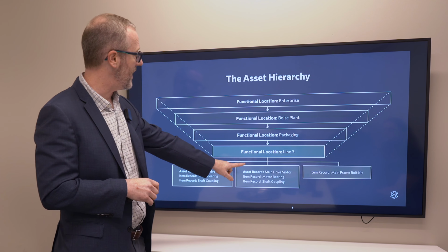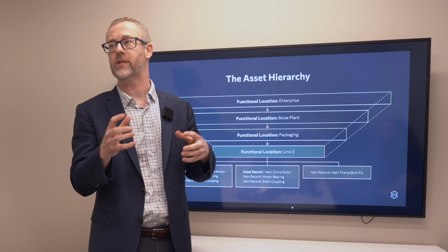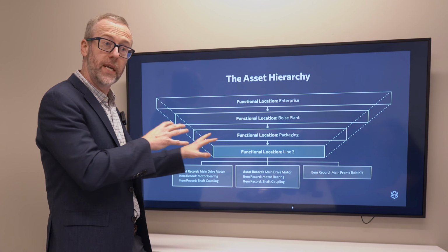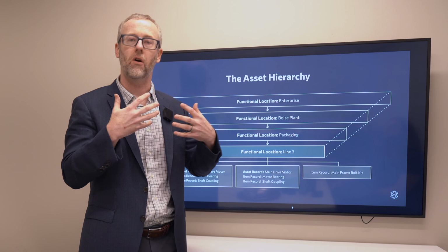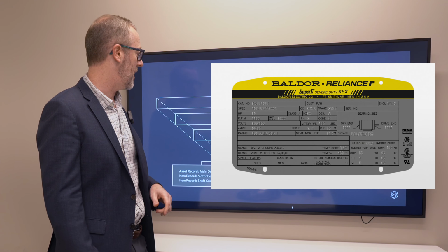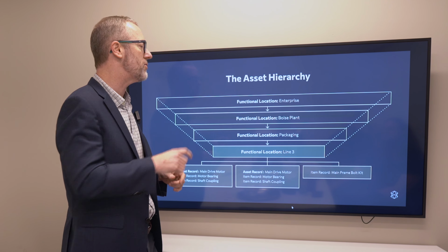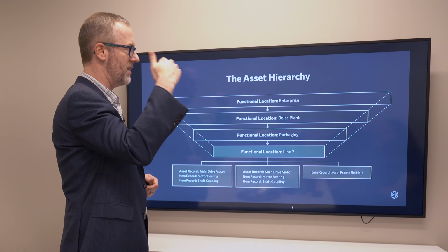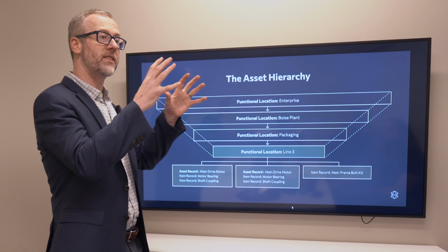The type of information that we need on the asset record is all of the technical specifications or the nameplate details about that asset. Because now, for the asset, this is where we're launching our work orders, so we need to know literally what is the make, what is the model, what type of bearing is it using, what is the size, all of the specifications that you would typically find stamped on the side of it, on the nameplate. You would call this the nameplate. So if you were to go up to the side of a motor, 99 times out of 100, you'll see a literal metal tag stamped on the side, and it has the NEMA size and the voltage and the current and all of the specs that you would need about a motor in order to do work on it. So that's the asset record.